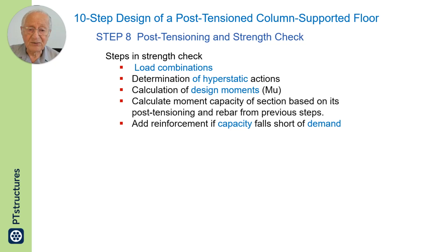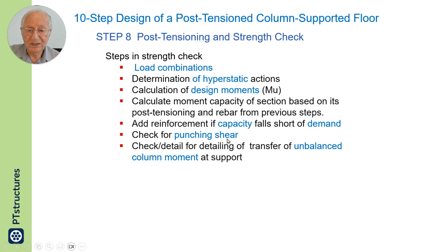In other words, rather than doing design, by that I mean calculating how much rebar you need, you calculate how much capacity you have and compare it with demand. After that, we do a punching shear check, which is required.